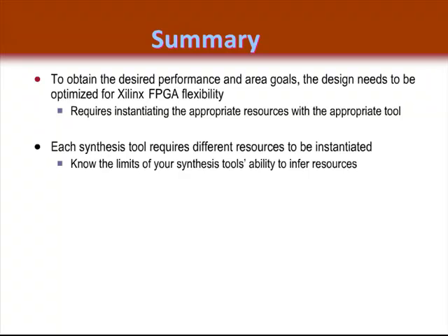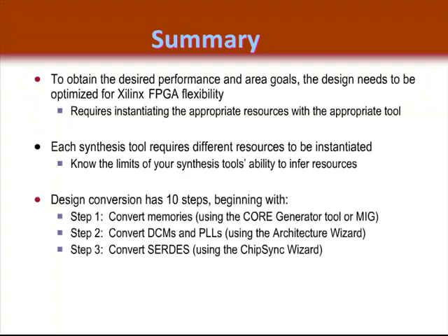However, if you want to infer resources, most architectural resources are inferable in some form. The additional challenge will be for you to know the limits of your synthesis tool, what attributes you might have to assign, and if there is any particular coding style that is required. Finally, we started our 10-step guide to design conversion, and we got through the first 3. And we'll continue with this list in our next REL.